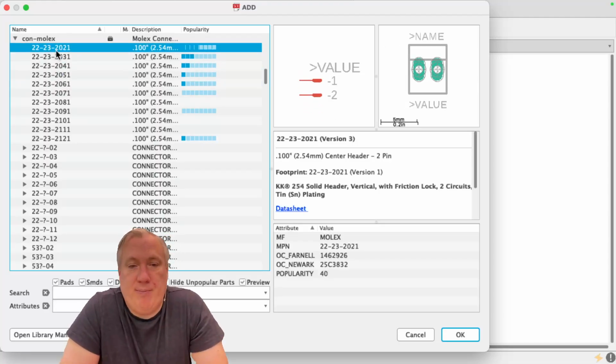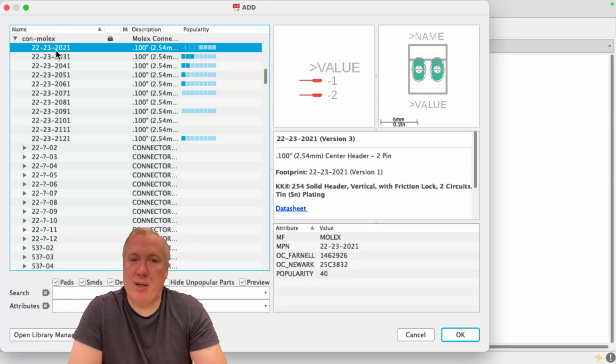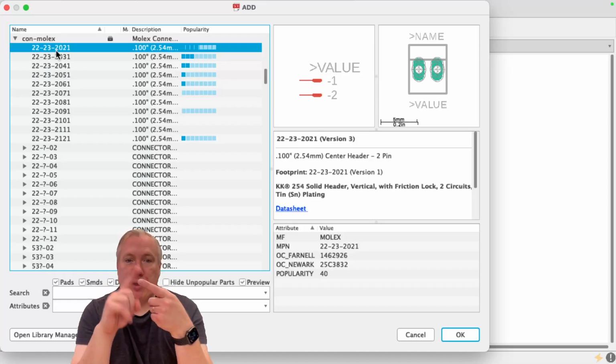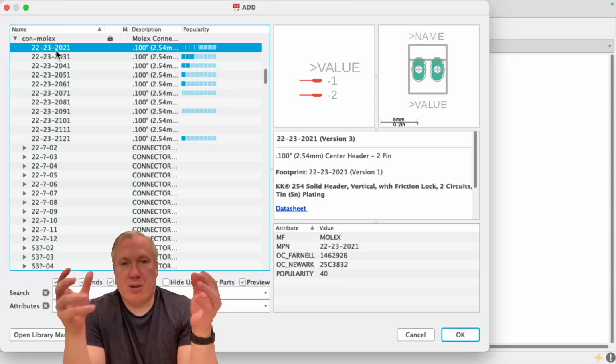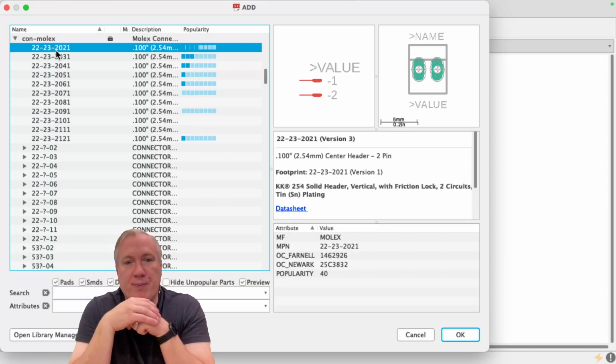Now, you'll notice that there isn't a 1-pin connection, and that's because in order to have a circuit, you have to have something going out and something coming back in. And typically, for a simple circuit, that's power and ground, or signal and ground. Always ground is included in one of those two. That's the 0-volt reference point. It's the return where everything comes back through.